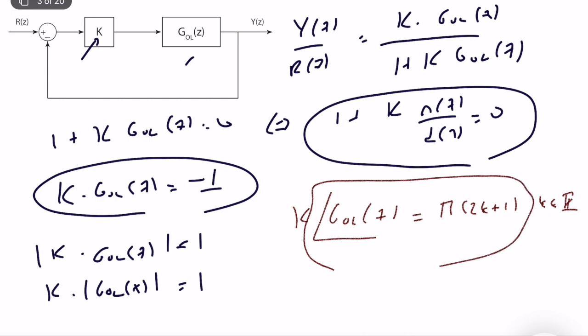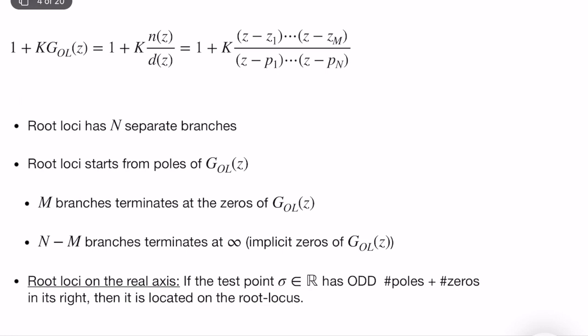I really recommend you go over your notes from 302 and look at the Root-Locus notes from this course's lecture notes to remember the basics and fundamentals of how we can write the rules. In today's lecture, I will review the resultant rules and we will solve some examples. So let's remember some of the rules. The first thing you should do is write your open loop transfer function in terms of poles and zeros like this. We have n many poles and m many zeros. So the number of zeros is equal to m, and the number of poles is equal to n.